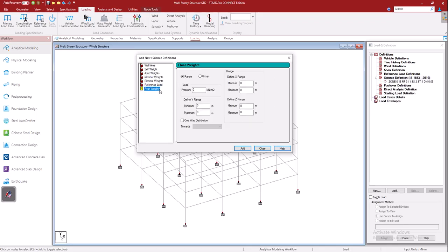After this, I need to add a floor load. In this floor load, we have a live load of 3 kilonewton per square meter, and we have a slab. If you calculate the slab load, it is 150 mm, which is 0.15 meter, times 25 density per square meter of area, which comes out to be 3.75.